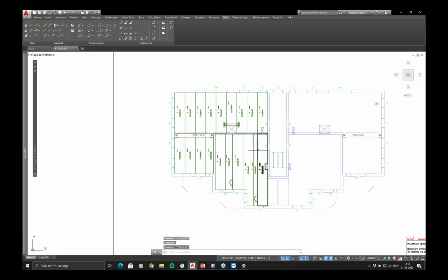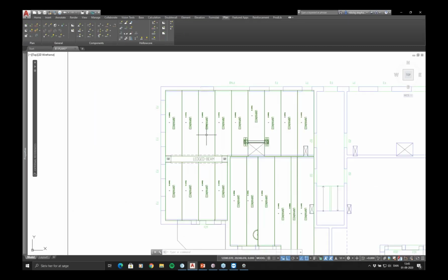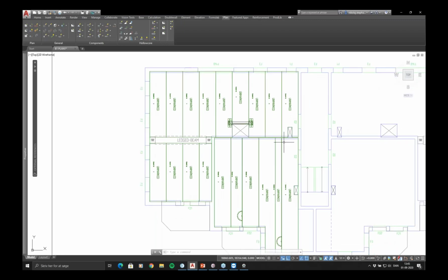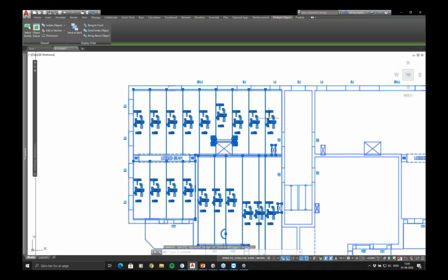So before actually adding more detail, for a lot of you, this is how you actually detail your hollow cores. You cut them straight at the ends and you lift them up with lifting clamps. And in that case, we don't need extra lifters or anything like that. So what I'll do is I'll take these and I'll mirror them.